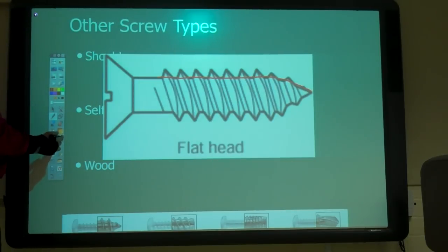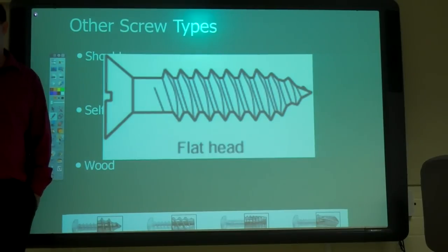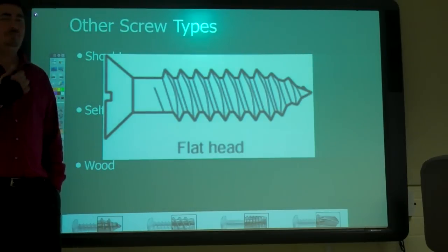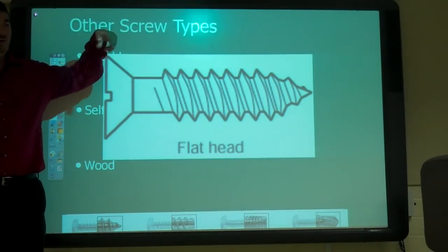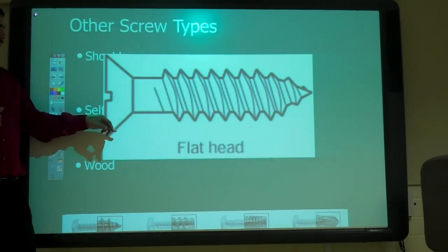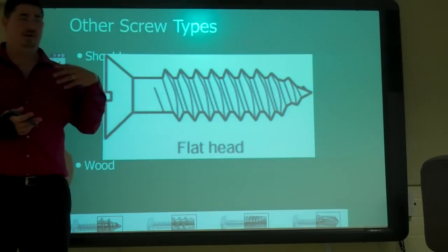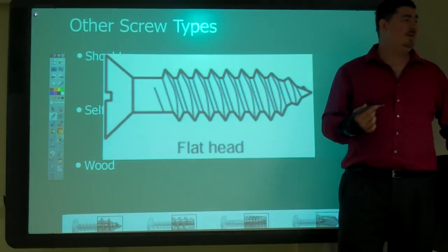Do you have to pilot drill all wood screws? No. When do you need to pilot drill it? What makes you decide if you need to do a pilot drill or not? Don't want to crack it. If you don't want to crack it, but also what determines that? Some type of wood has the biggest part of it. So part of it is if you're going to be close to an edge, you definitely want to pilot it, or if you've got a couple things. But depending on the wood, if it's a real soft wood, you probably don't have to pilot it, even if you're right next to the edge. But if you're on a real hard wood, you better do it.